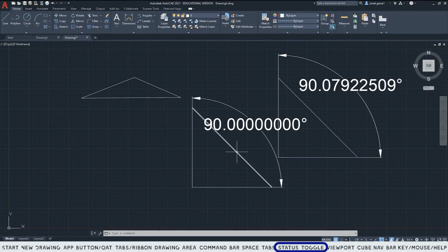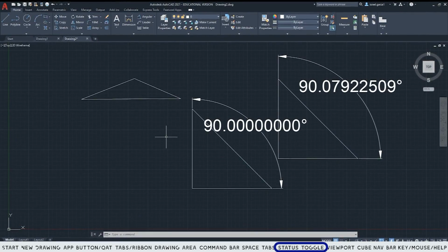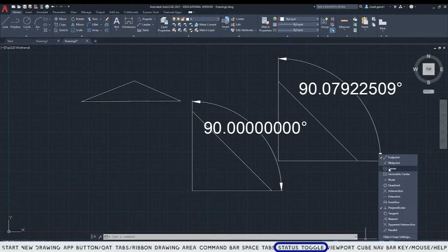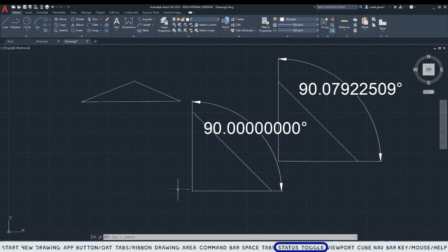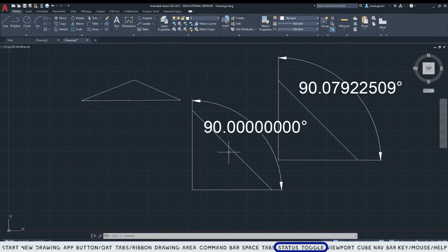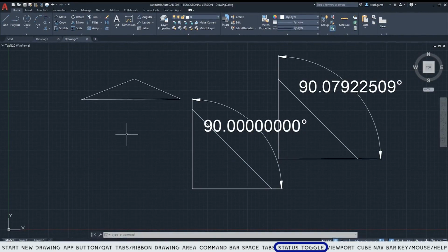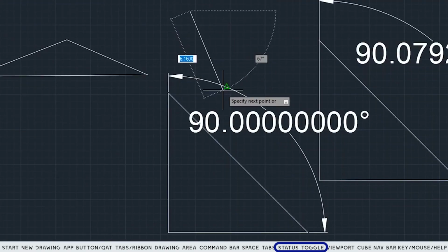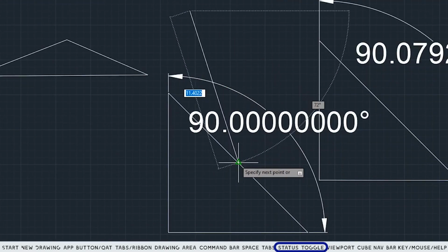So what if I wanted to hit the midpoint of this line from another line? I can turn on another mode from O-snap. I'll turn on midpoint so that whenever I draw any line, it'll snap to the exact midpoint of this line. So let's give it a try. Click on the line. I'll start here and come down. Alright, so we can see that it snapped to the midpoint.